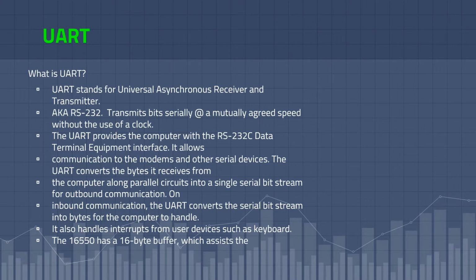Step 1. The transmitting UART receives data in parallel from the data bus. Step 2. The transmitting UART adds the start bit, parity bit, and the stop bit to the data frame. Step 3. The entire packet is sent serially from transmitting UART to the receiving UART.